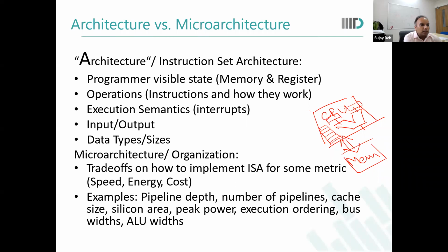This register file is nothing but a bunch of registers, which is nothing but memory, right? They can hold the operands which you need to work with. For example, let's say you are fetching a few operands or variables, A, B, and C. It has been observed, because of spatial locality and temporal locality in the way we access data, that if you are accessing a particular variable right now, it's very likely that you will be accessing that variable again.